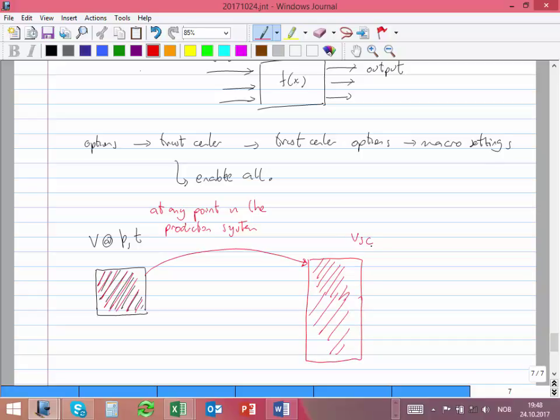So, volume at standard conditions, at P standard conditions and T standard conditions. Okay, so I can define, I want to have an easy way, instead of going and looking at the equation of state, to relate these two volumes: the volume at one particular pressure and temperature, and the volume at standard conditions. Remember, usually all of our volumes and rates use this reference, but we need these volumes to calculate things like velocity, friction, pressure drop. And I want to avoid going and using the equation of state.